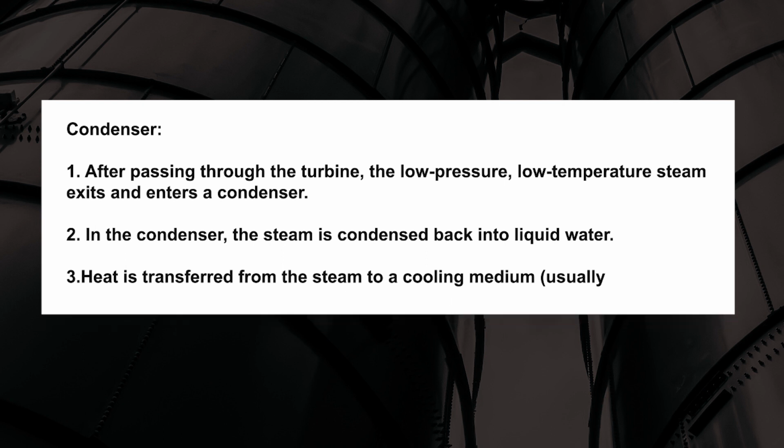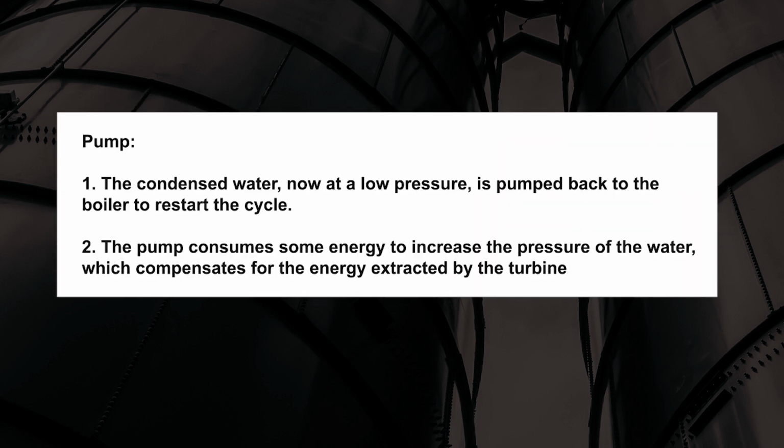the condensation process. Coming to the pump, the fourth component of the Rankine cycle, the condensate water, now at a low pressure, is pumped back to the boiler to restart the cycle. The pump consumes some energy to increase the pressure of the water, which compensates for the energy extracted by the